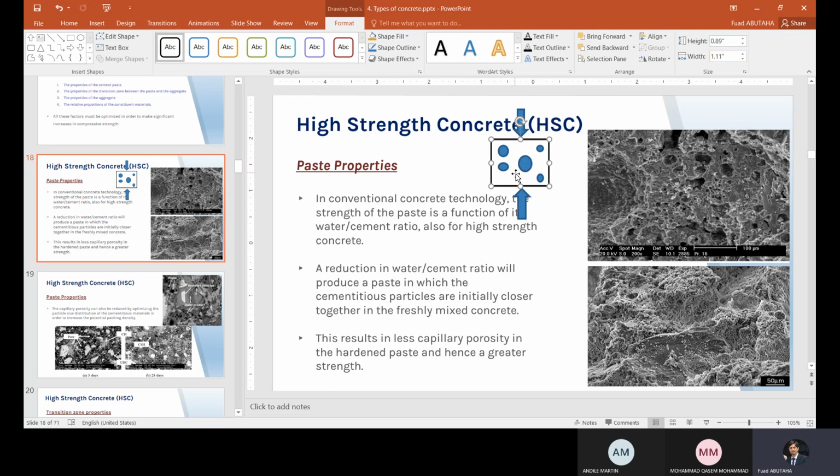You cannot just focus on one of them and leave the others. If you try to just improve the cement base and you achieve a concrete that has high cement base strength, but we have a weakness part here, the concrete will not struggle to break the strong base. The failure will go to the easiest part. The weak part here is the aggregate, so the crack will go through the aggregates.